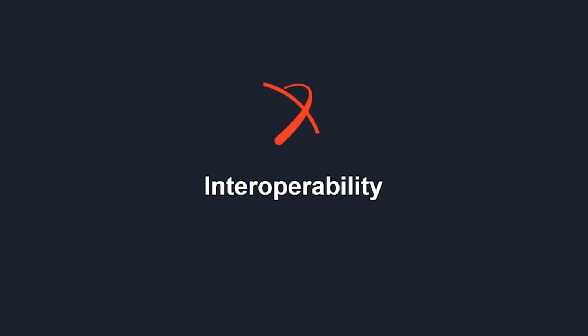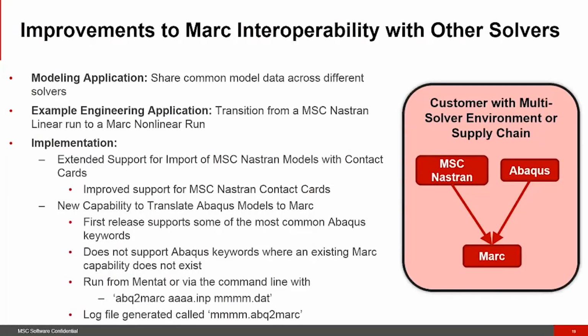So Marc 2018 provides significant improvements to allow a streamlined interface with MSC Nastran and Abaqus. For the MSC Nastran side, we can transition the model from a linear run to a nonlinear run in Marc. Please keep in mind that this is a literal translation and it is not going to give you a perfect model. It will just try to look up everything that it reads from Nastran and find the equivalent Marc entry. So it provides you some definitions.